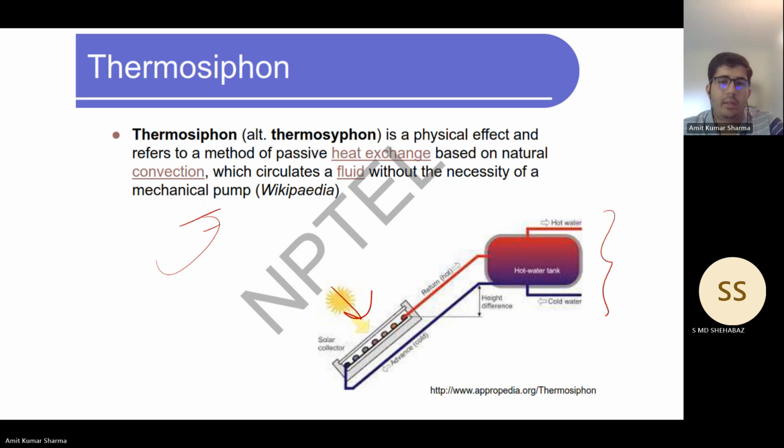It's very popular, and I think various homeowners have installed these on their roofs. Like, there is a water tank. So there is cold water on the bottom side and hot water on the upper side. The cold water flows through these tubes, and due to the sun rays and the upper glass layer, the heat is trapped inside this glass box, and that heat heats the fluid through these tubes. And the hot water will flow again to the tank,